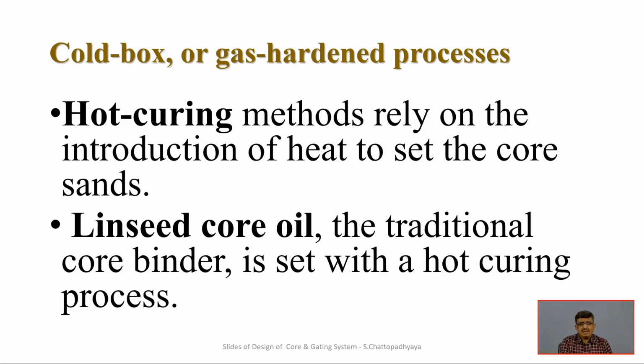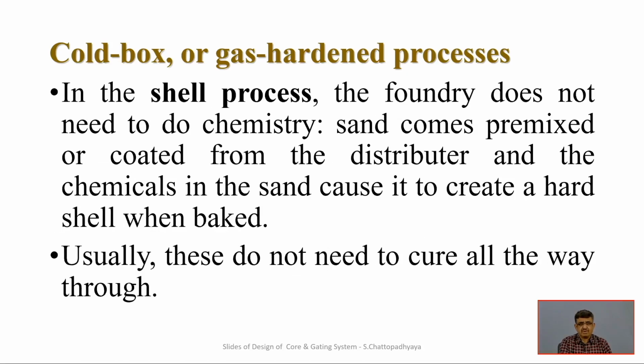And there are methods of hot curing, because at elevated temperature the binding will result in more strength, and that method relies on the introduction of heat. And linseed core oils, an additional core binder, are also set with a hot curing process, so that at elevated temperature, with the random motions of the molecules and atoms, the binding becomes stronger and stronger, which is very crucial for retention of the strength of the core even at high temperature, or imparting hot strength to those cores.